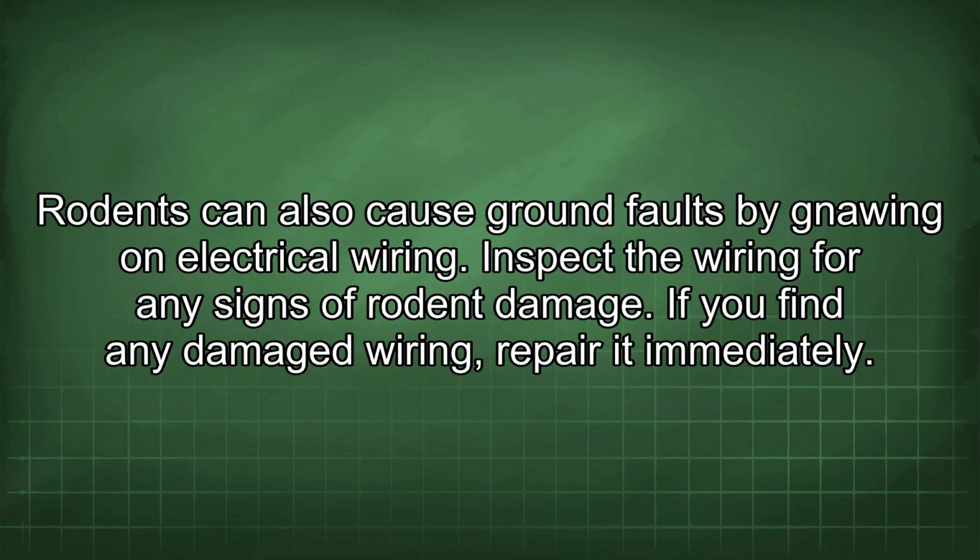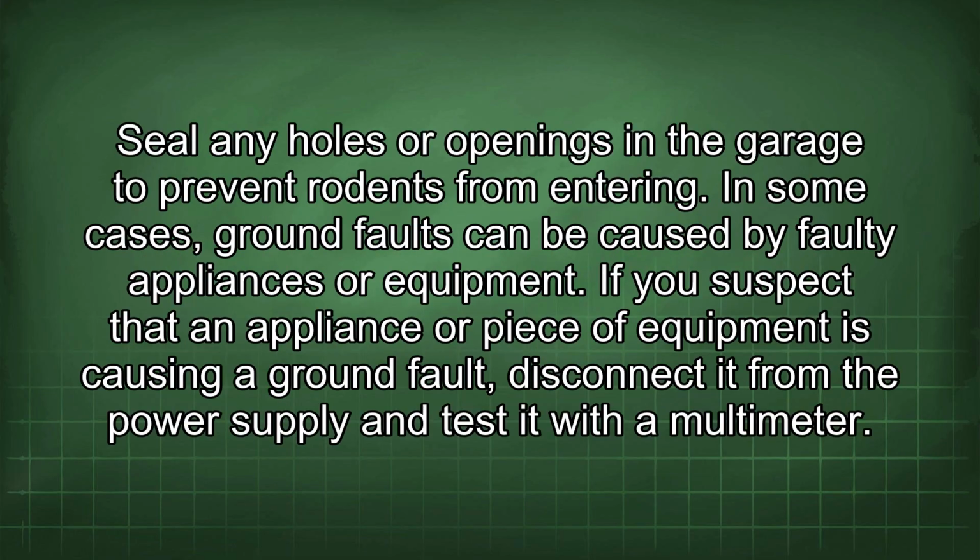Rodents can also cause ground faults by gnawing on electrical wiring. Inspect the wiring for any signs of rodent damage. If you find any damaged wiring, repair it immediately. Seal any holes or openings in the garage to prevent rodents from entering.